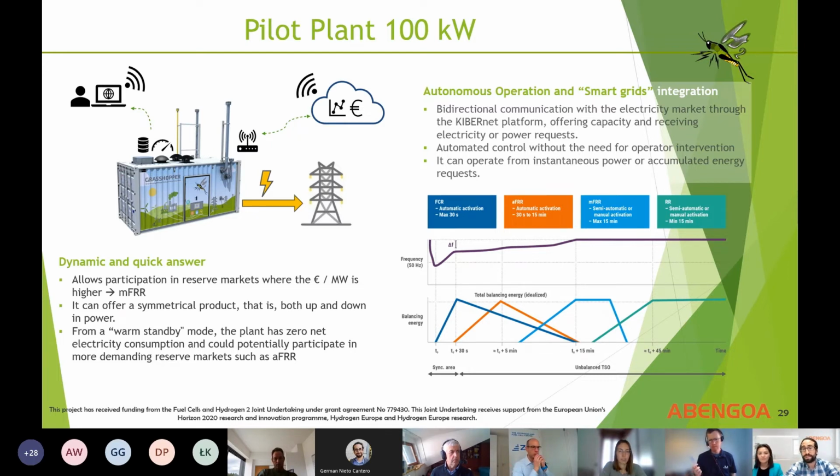One of the key aspects of the project is to participate in the electrical reserve market. The main reason is that usually this service is paid at a higher price than baseload generators. This would allow hydrogen fuel cell power plants to penetrate sooner as a commercially established product, as Ainea has said before. We have selected the European manual Frequency Restoration Reserve. Probably you all know that each country has its own shape of the reserve market, but they are unifying into automatic frequency restoration reserve and manual frequency restoration reserve.